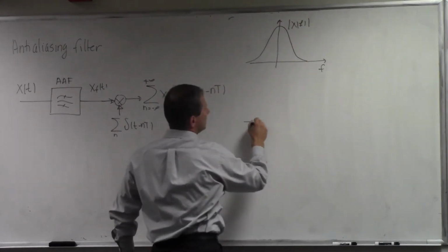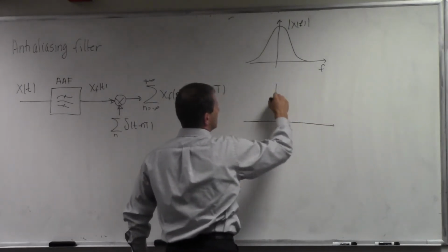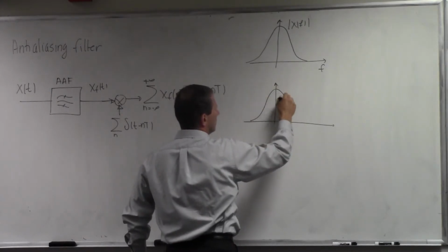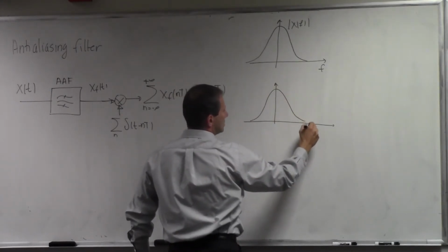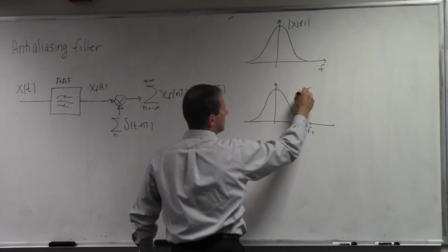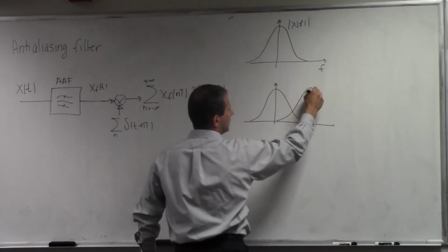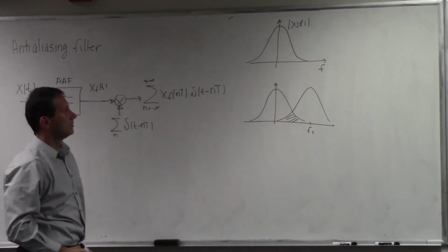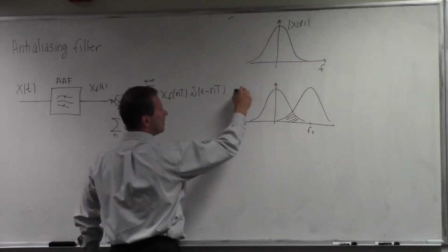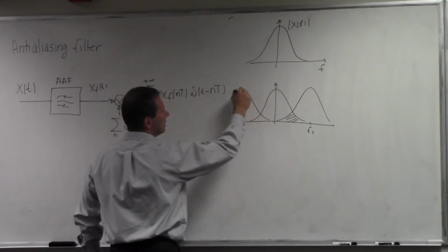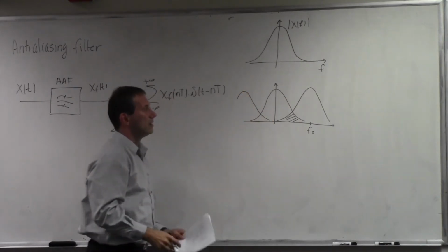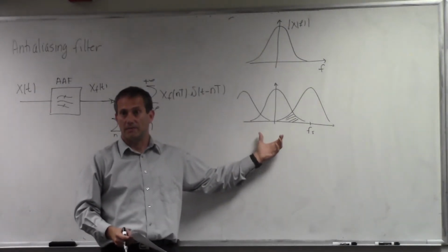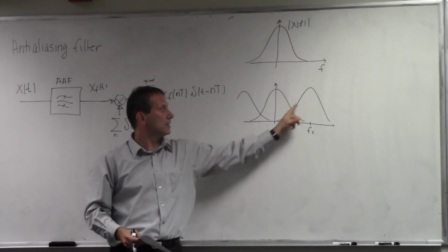If we sample this signal, as a result of sampling, the signal is extended periodically in the frequency domain. So let's say this is your sampling frequency. As a result, you end up having something like this, right? And in this range here, you have a mixture of the frequencies coming from the baseband version of the signal and its periodic extension. Therefore, your reconstruction becomes impossible here. You have a mixture of this signal and this signal.